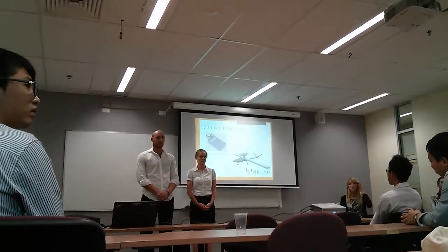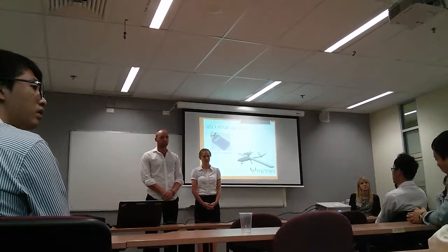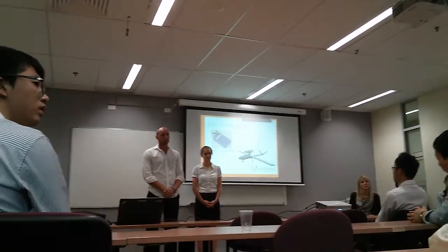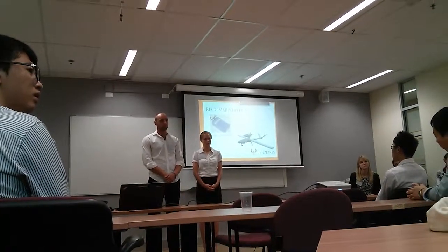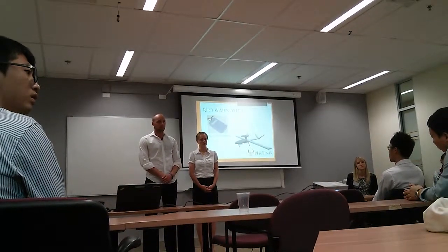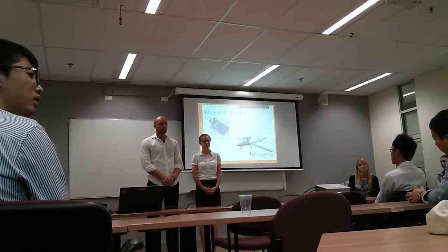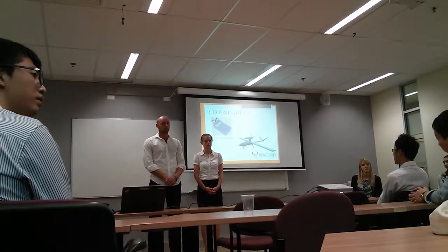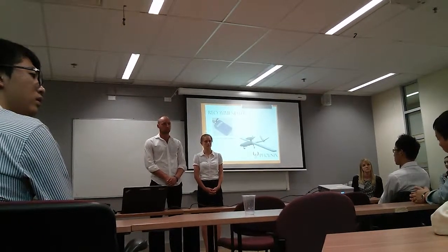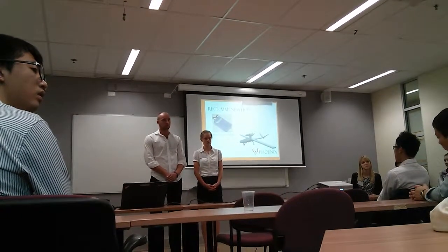Yeah, so if you can get this information without adding weight, because if you add a LiDAR system for measuring altitude, you need to weigh up how well you need to know your altitude. LiDAR is a very accurate device, but is it absolutely necessary? Because you're going to bolt on something that might weigh half a kilo, and for your UAV, every kilo adds to the wingspan. It's a very non-linear effect. Everything gets more complicated.